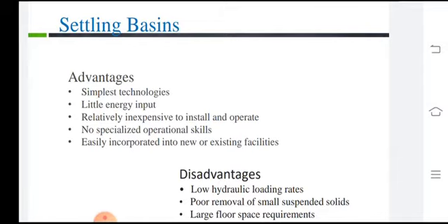However, we can increase these densities, and we can coagulate these particles to join them to make flocculates, and this combination, this floc, will have a higher density, and it will facilitate the downward movement under gravity.